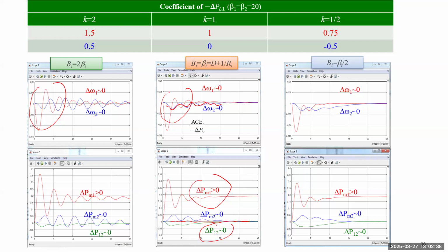When k is only 0.5, what's interesting is the second unit simply doesn't want to do any active control, and you see this curve will basically just stay under the nominal frequency. It even increases the deviation of the frequency, but eventually, after taking a longer time, the system still goes back to roughly the original frequency. Even if it may not be, because this is AGC, eventually we'll go back to 60 Hertz.